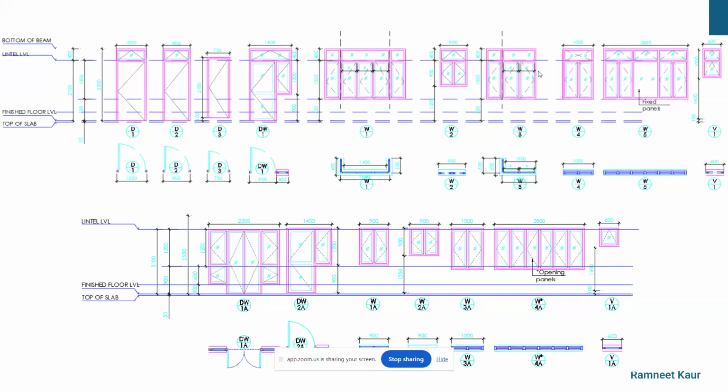However, if you look at how this W1A compares to W2A and W3A, they are basically look-alikes, but just their sizes are different, right? Similarly, if you look here, D1 and D2 are very similar. However, the difference is only in their sizes. Also, sometimes we want to create doors and windows, or probably bay windows. So basically, families, once created, can help you create your own library, which can be repeated over your projects, or which can really improve your workflow.